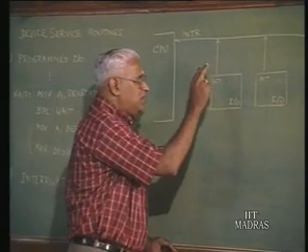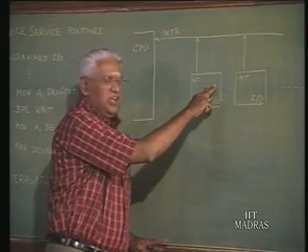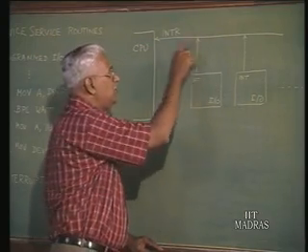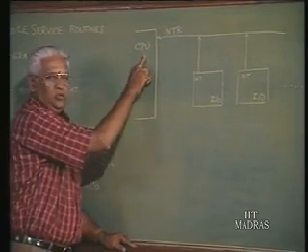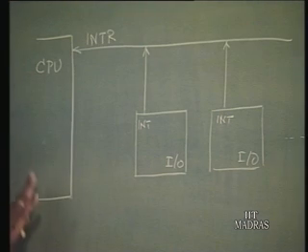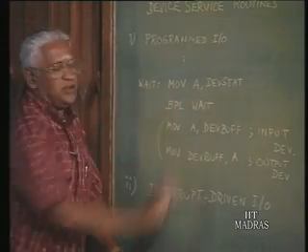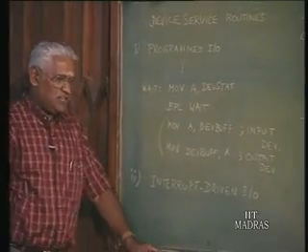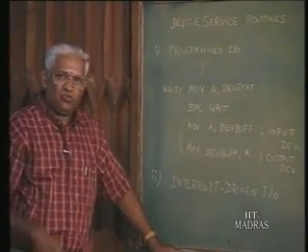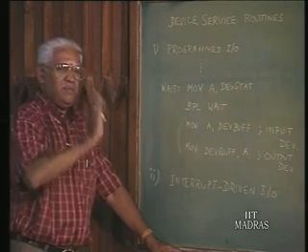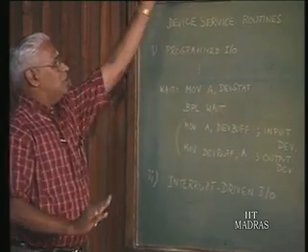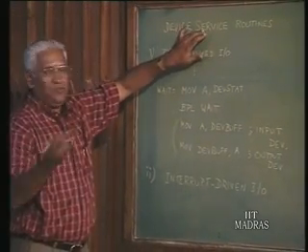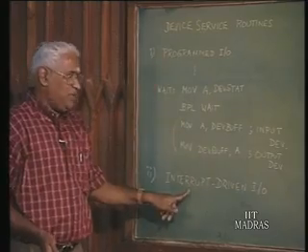So, when the input device data buffer is ready, it is going to interrupt. Now, the CPU is going to stop whatever it has been doing, and it has to turn its attention to this service part, device service. So, we said earlier, in the case of interrupt driven IO, there is a context switch, that is a switch from the main routine to the device service routine.